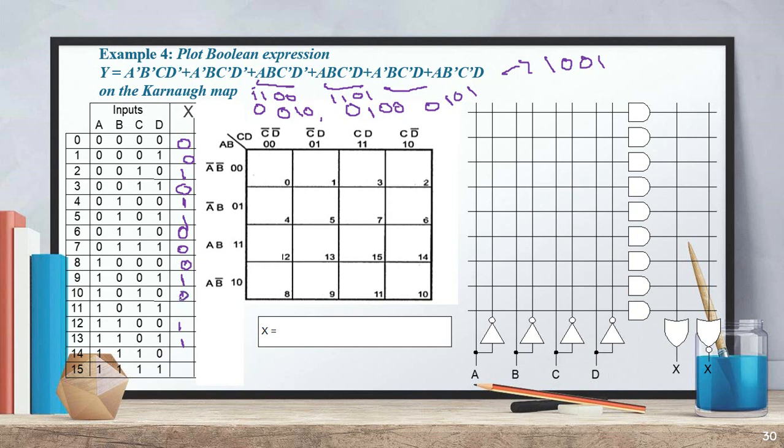In the truth table, always remember to first fill the 1s, it is easy. Wherever it is not present, make it zeros. Now fill the KMAP with the truth table. So the 1s present are at 2: 2 is 1, then 4 is 1, then 5 is 1, and then 9 is 1, then 12 is 1, 13 is 1.